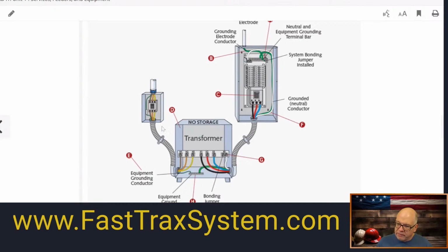And again, if this was an FMC and that type of thing, depending on the size of it, you may have to bond it. Or if these fittings are all listed and this is a punched hole, not a concentric or eccentric, where you actually cut this hole, then it may or may not be necessary to have any type of bonding bushing here. Okay. This depends.